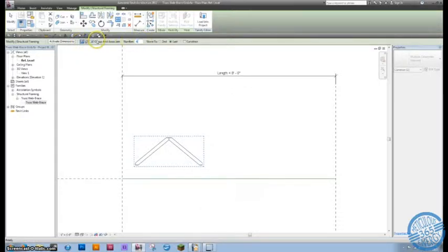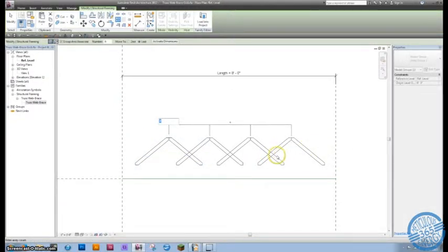I will use 4 elements here because that will immediately show me what's happening with this second last. If I put in 4 elements and they fall off the screen, that's because they're going first to second, and then they're going as far as I want them to. If I do first last and I provide a short length, then you will see all of those elements fill in. So we will just do a short distance that way. This is exactly what we were looking for. It's a proper first last array.